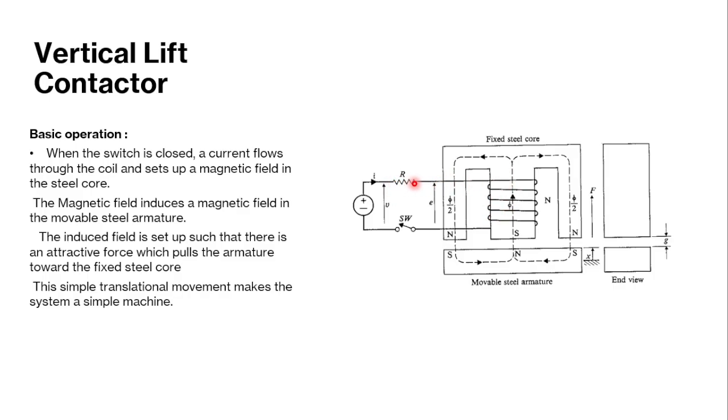So when you have this current going through the coil, you have a magnetic field being generated. And when you have this magnetic field being generated in the magnetic circuit now, that MMF is going to give you a flux also, and the flux is going to emanate out in this direction. So we did the right hand grip rule, so we know the direction it will go in. So when it goes, it splits. Most of the time, the two end pieces will be half because you want it to be symmetrical.